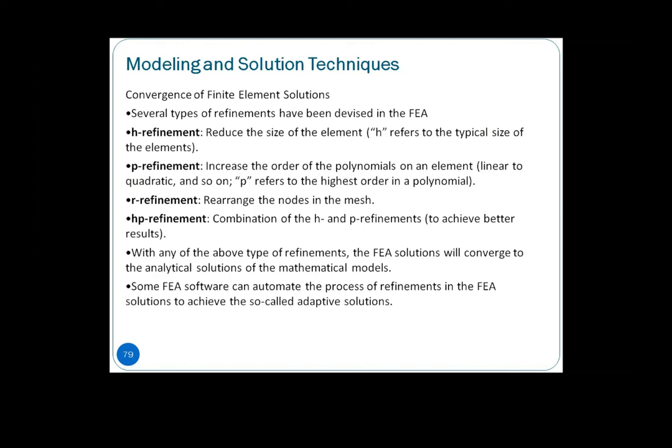What you can do is change the mesh size, or however you mesh it, in terms of sizing, the way it is arranged, or its order. You have to change it until you get consistent results. Let's say you are looking into displacement. You may start with a size of 0.2 mm, then slowly reduce the size and get higher accuracy.